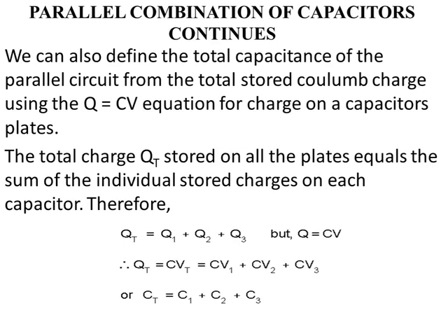Now see those V's, since they are all the same, eliminate them. You will be left with your C1 plus C2 plus C3 plus C4. So even if you are trying to get your total capacitance from your charge, you will still come back to having the same thing. So either you get it from using Q equals CV, or you just do directly C1 plus C2 plus C3 plus C4. You will be having the same total capacitance for your parallel combination.